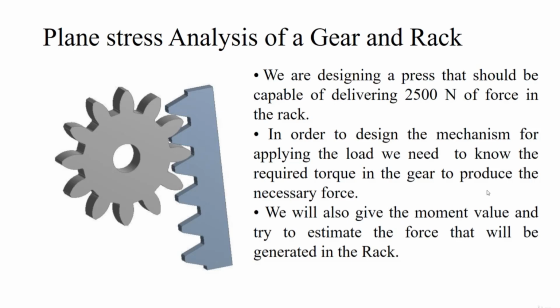Reducing the problem to 2D has many advantages. For example, we can build a simpler geometry, we can build better mesh quality, we require less computational time, it is easy to display and analyze results, and sometimes, if you don't take any other assumptions, we get more accurate results when compared to the 3D one. So in short, we can say that 2D simulation models will help us to handle these simulations much better.